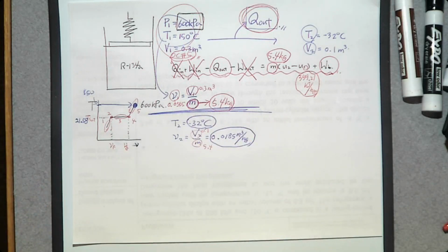So we have temperature and specific volume. Can you determine the phase change process? Oh, wait, we already have two property values. Can you just determine the phase change process here? No, you can't, because you need two intensive properties. That capital V is an extensive property, so you cannot use that capital V. You can use specific v. So we have minus 32 degrees Celsius and 0.0185.